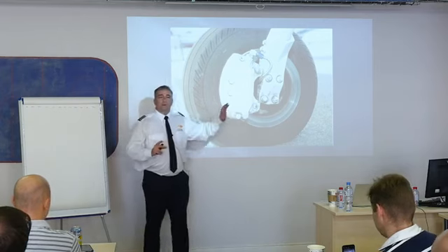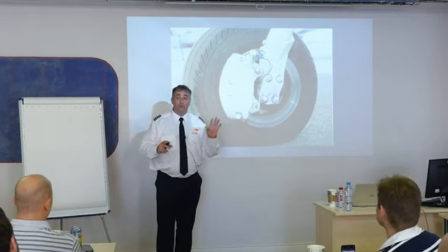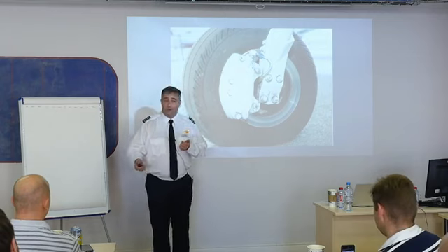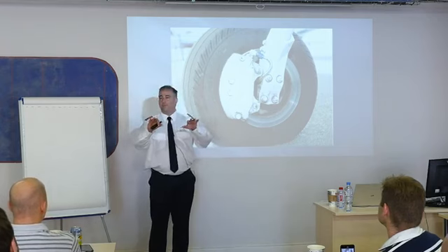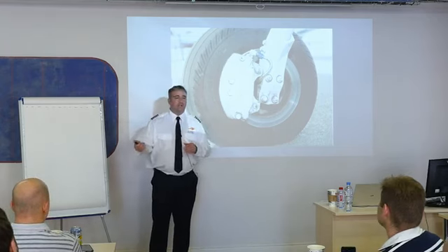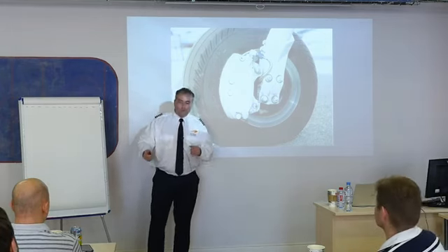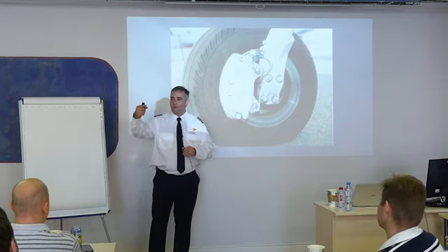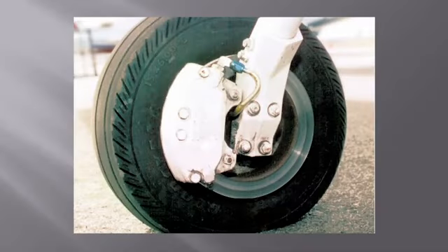The other thing is, when you're taxiing, not the taxis, Uber and all that, but when you're taxiing the airplane out to your runway, don't put your feet on the top of the pedals. I see it all day long. You got the airplane at 1,500 RPM, making all kind of noise, and the airplane's barely moving, and they got the brakes on. Don't do that. You're just putting a lot of heat on the brakes. If I need those brakes for a rejected takeoff, they're not going to work as well as they would if they were cool. All right, a couple things about brakes and brake systems.